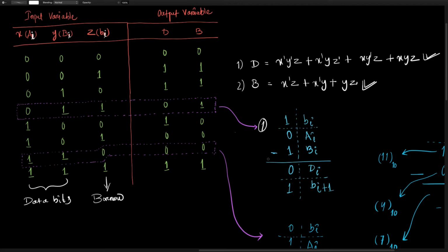Now, if you want to calculate the difference of these two, this stage says that we have a borrow. One borrow has been requested by the previous stage. So we can say that here 1 was taken, but as there is 0, we cannot take 1 from there. So 1 should be taken from its previous stages. If 1 is taken from its previous stages, this stage exhibits a borrow, which would be transferred to the next bit, that is b of I plus 1.